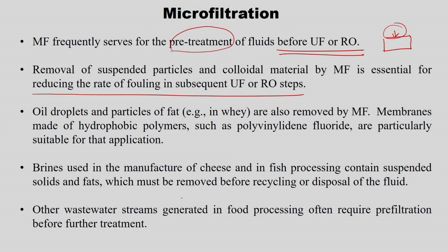So, as I told just now, when you do this microfiltration operation, these unnecessary large size molecules get eliminated here, but if it goes directly to ultrafiltration, there is unnecessary fouling, or it gets clogged on the membrane surface. Okay. So, that can be avoided if we use microfiltration before ultrafiltration or reverse osmosis. Oil droplets and particles of fat, an example being whey, are also removed by microfiltration.